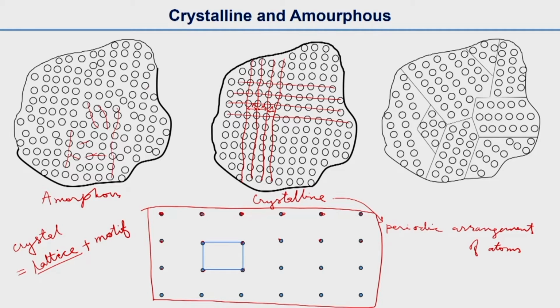See what I showed you earlier here: these are atoms, and I am sure all of you understood this. But here, what we are showing is mathematical points. The array of these mathematical points is called the lattice. And these lattice points, as you can see, are arranged at equal intervals, whether you look at it this way or this way. So the lattice is only the mathematical points, and the motif is one or multiple atoms.